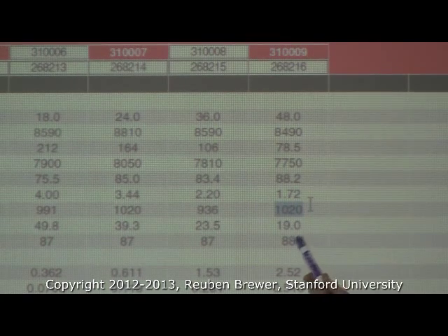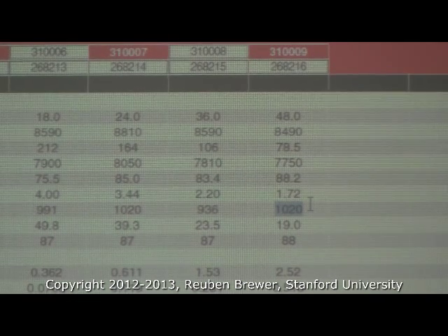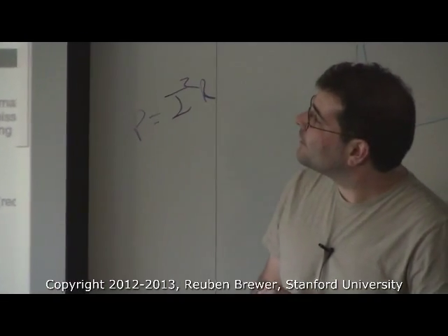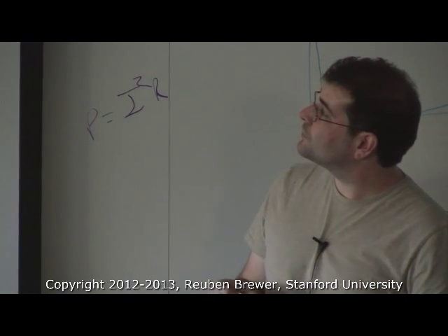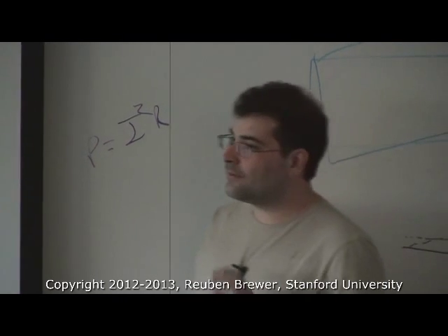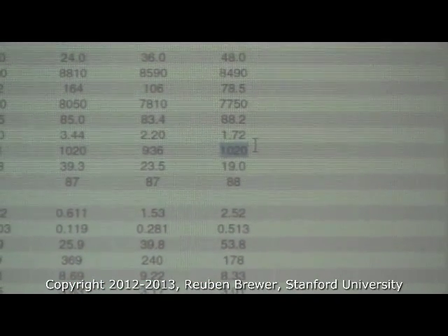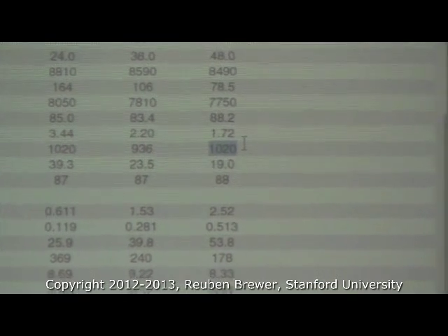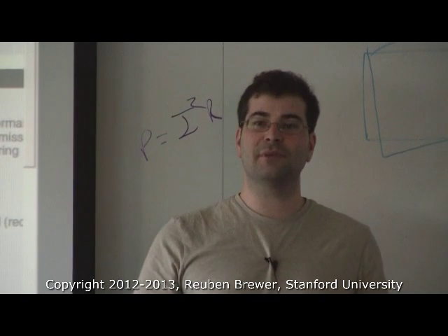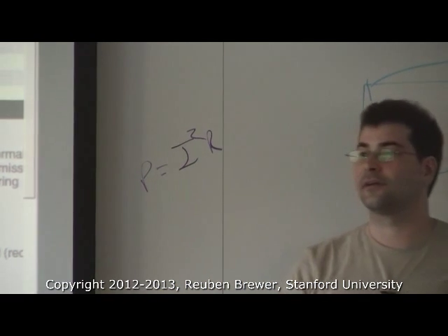What the peak current is good for is this: the cleanest way to get more torque is to have a bigger motor. And for haptic devices, you would like to show, hey, we're able to render huge forces. If in your calculations for a paper you use the max continuous current, your haptic device looks terrible. If you use your peak current, it looks great because it's a factor of 10. So people always report the peak current in their papers on haptic devices because it looks great. But if you were to plug in their haptic device, it would set on fire.